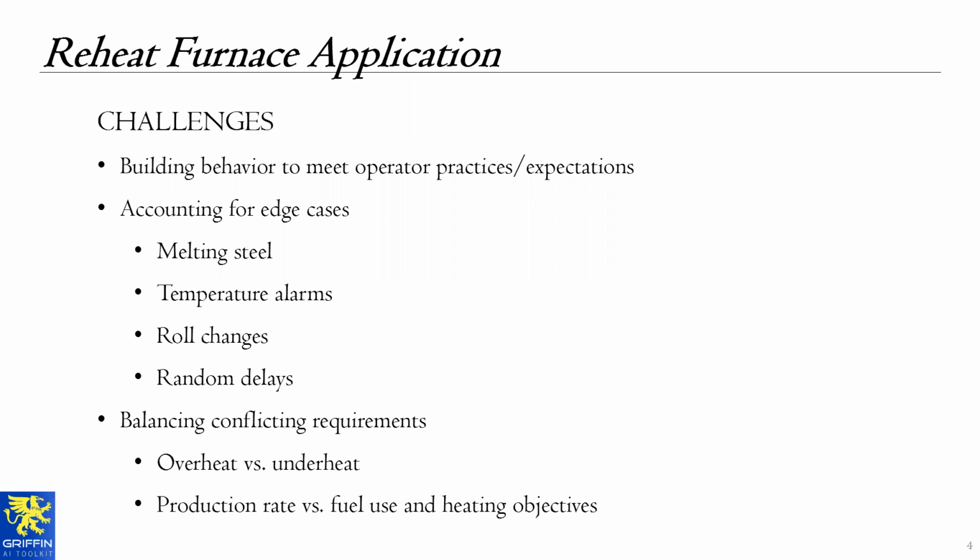So I bumped up the temperature limits to 2,440 because I'm trying to get this to run as fully automated as possible. And then it turns out another day we're sitting there at 2,440 and the steel starts melting and dripping down into the underbody of the furnace. That's clearly not desirable either. So I had to put in a whole different set of logic for checking steel temperatures and making sure they weren't going out of bounds.